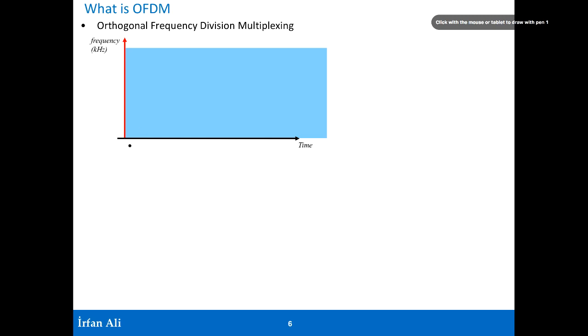And as we said, we look at the time frequency domain. So we have time on the x-axis and frequency on the y-axis, and the frequency is in kilohertz. So we have 15 kilohertz, as we said. The subcarrier frequency in LTE is multiples of 15 kilohertz, and that's how the design was chosen, to have a base frequency of 15 kilohertz. And we will look at this 15 kilohertz signal and its harmonics over the base time period of this harmonic, which is 66.67 microseconds.